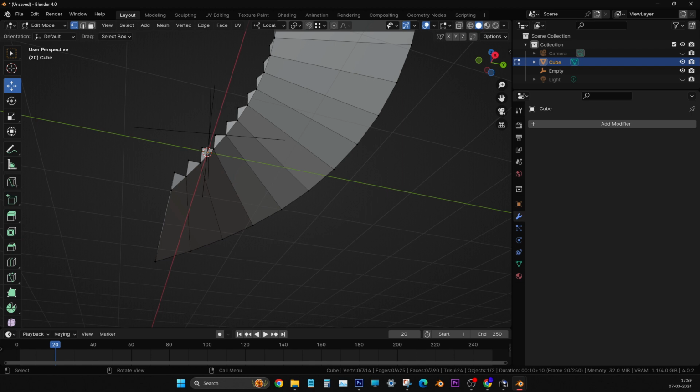Enter. So now see, 154 vertices are merged. It just showed. So always, when you are typing, see that it will show you the result, how many vertices are removed, so that many double vertices became one vertex.